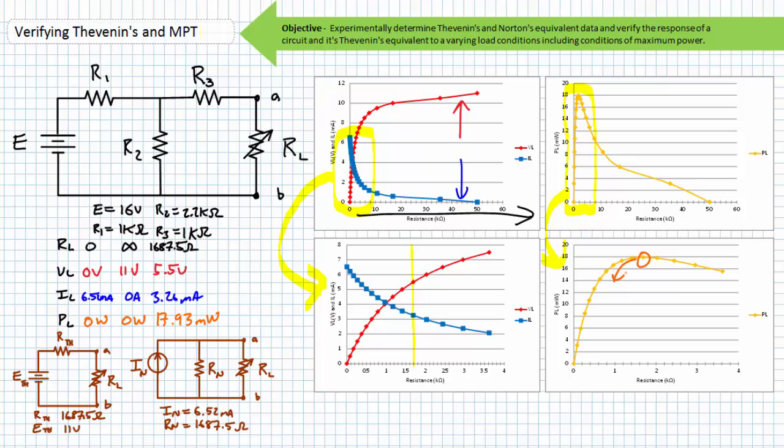Regions on the low side shoulder of the peak experience more current draw but less voltage drop. Regions on the high side shoulder of the peak experience more voltage drop but less current draw. The maximum power point is a compromised condition in which two interrelated voltage and current values form a maximum power product. Alright, I believe we accomplished what we intended to do for this lecture.